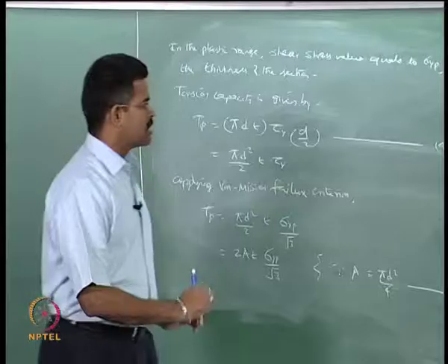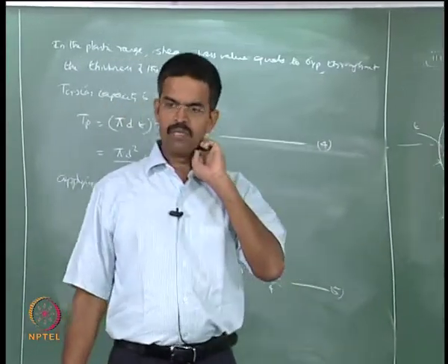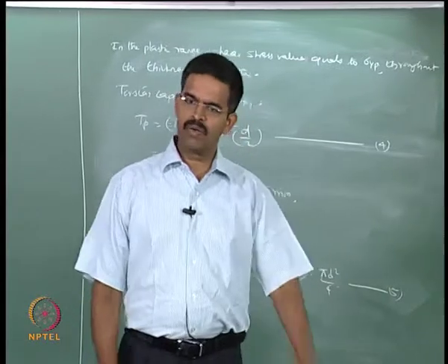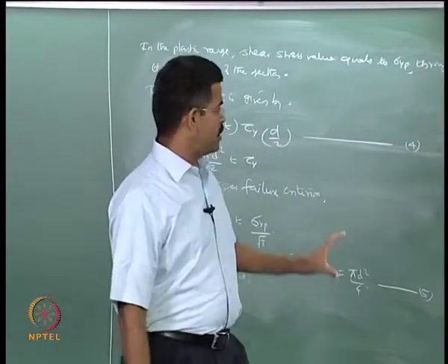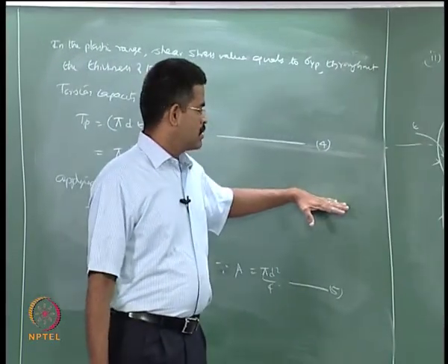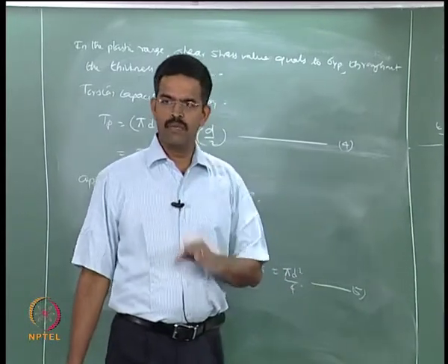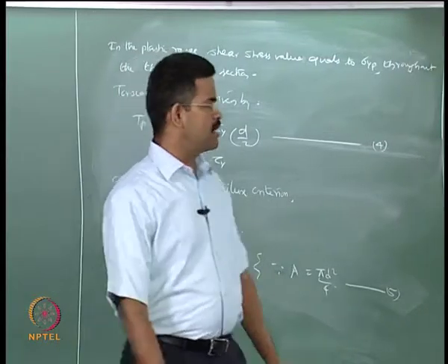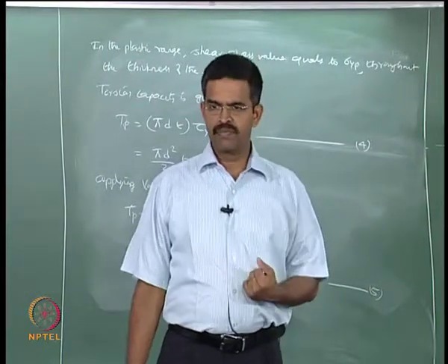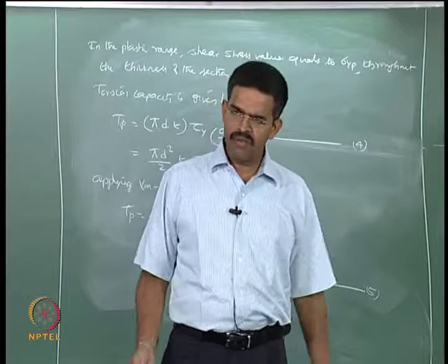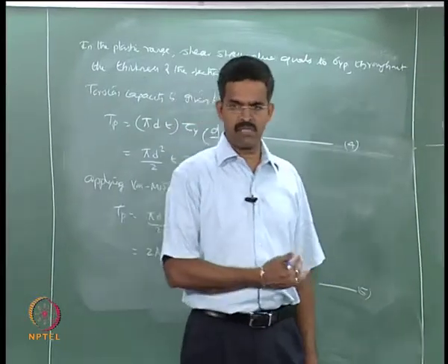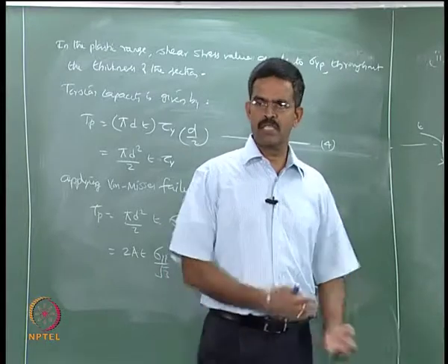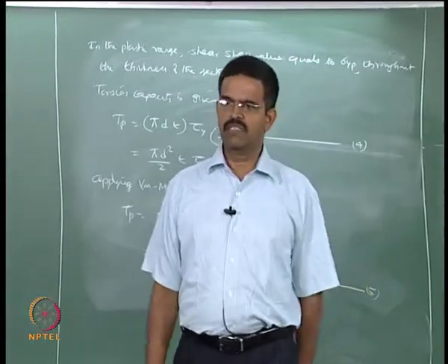Okay. So, in this lecture we discussed how to estimate the torsion capacity for different sections, open and closed, for different standard cross sections in geometry being used as members in marine structures. What would be the necessity of studying the buckling effect, because then we eliminate the buckling effect if the section is declared a compact section or the compact limit is proved or established, which is given by the expressions and equations as we discussed in the lecture.